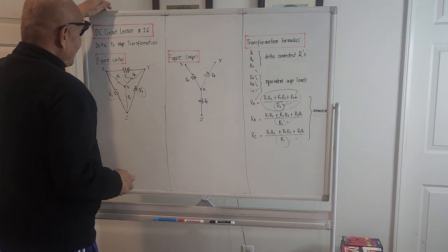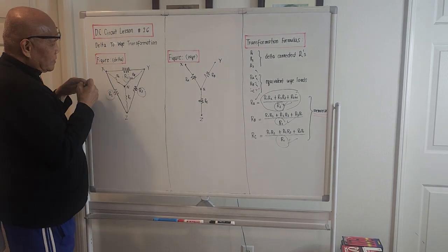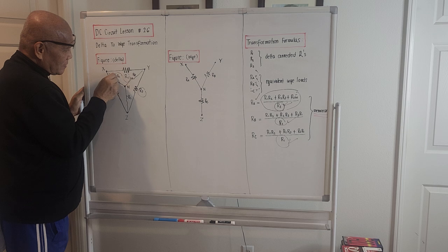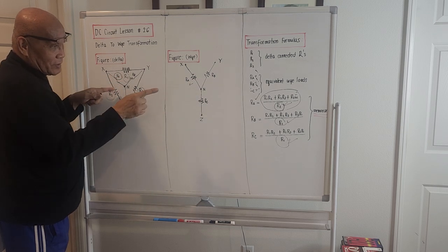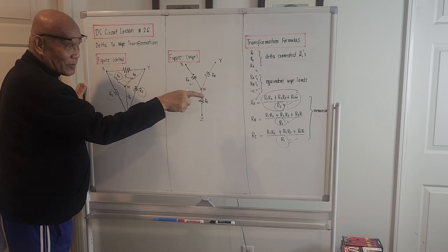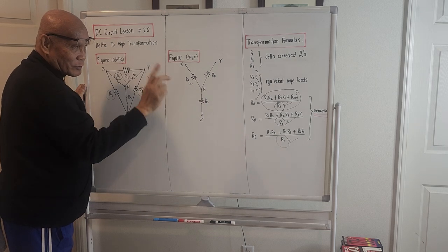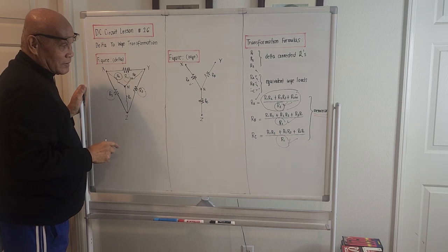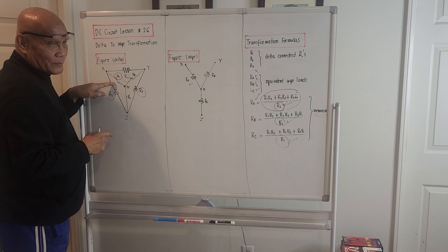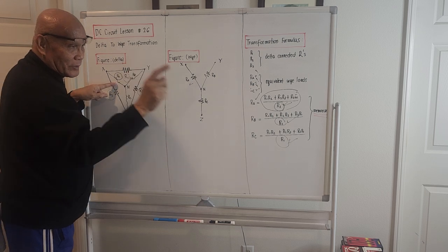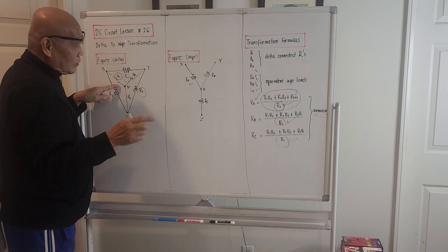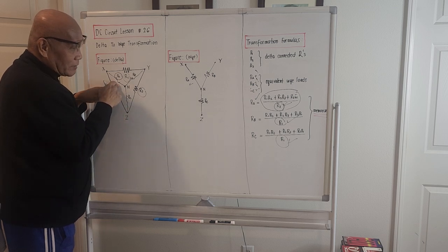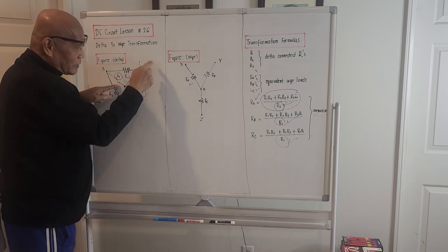If we try to compute for R sub A, this one, this is the Y equivalent. The numerator will be the summation of the individual products of the three resistances, right? But to compute for RA, the denominator should be the resistance opposite to RA considering the delta connection.